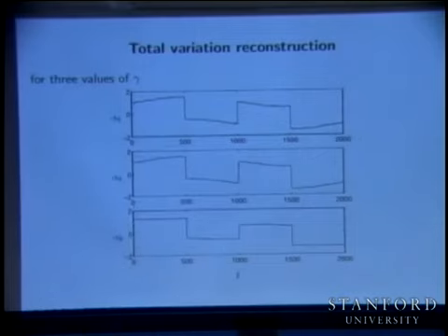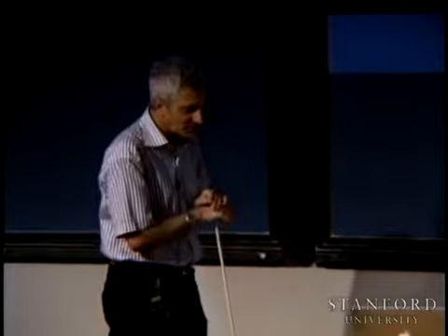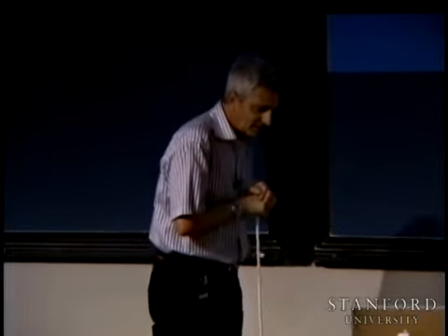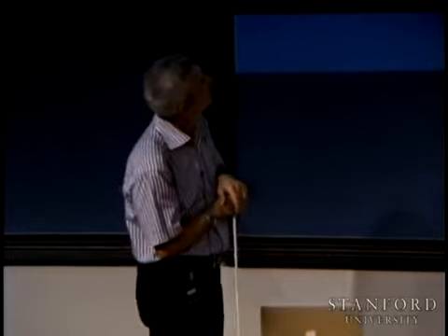By the way, I should probably produce some little audio files or something like this, so you can hear total variation denoising. It's very impressive. L2 denoising, in a minute we'll see that, is just low-pass filtering. You cut the high-frequency stuff, and everything just sounds muffled. You hit a drum, everything's muffled. The L1 method will actually cut out this high-frequency noise, but when someone hits a snare drum, it's right there. So it's pretty impressive. It'd be fun to do that, actually.